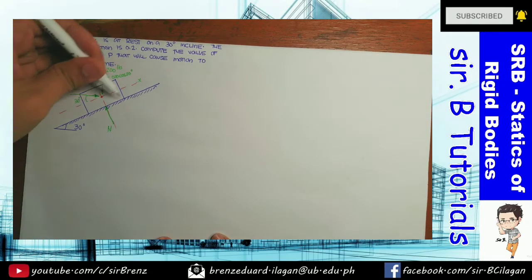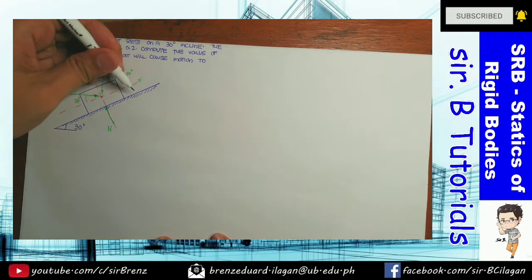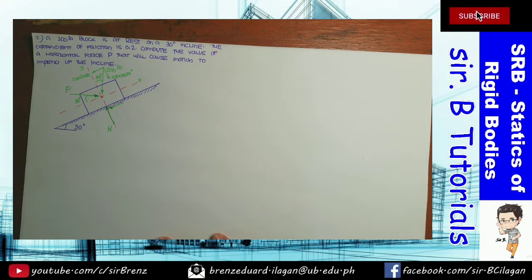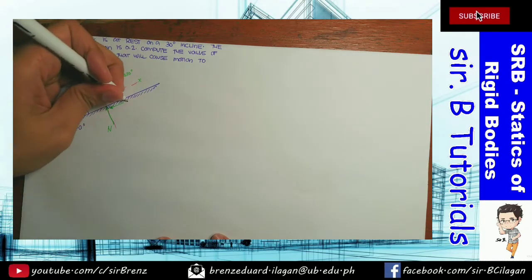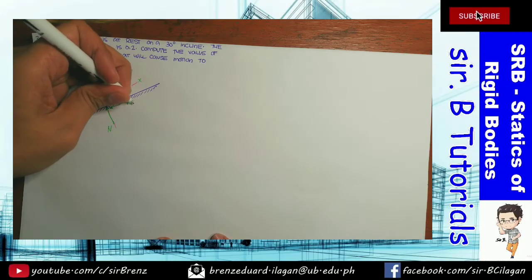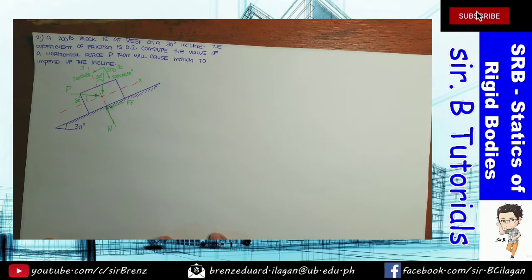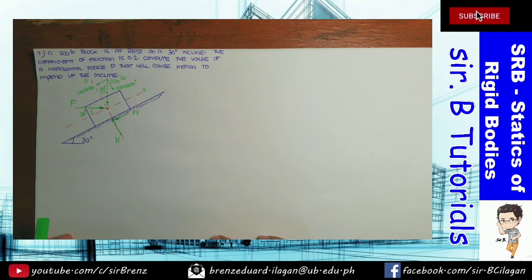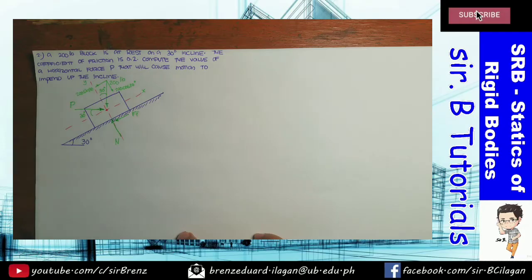So its movement will be going upward. Therefore, to prevent that, again, your frictional force, the resistance, is always opposite the direction of the motion, or the tendency for it to move. Okay, so here I will show you the two ways you can solve this. There are many ways to attack this problem. Again, this is just an application of equilibrium of a force system.